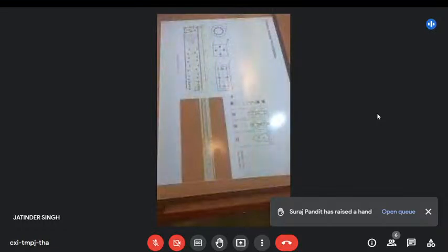But yeah, the flow, the spacing between them, you can see the inertial forces actually seem to adjust the spacing between the particles as well, based on the drag forces they leave behind. So you get a very nice and even train of particles, which makes it very predictable at what flow rate you need to work if you know the volume of these bubbles. So you know what volume you need to push out to form a single bubble. So there's good engineers that do the maths there, and then we need to run that 2.3 microliters in it, and we're good to go.